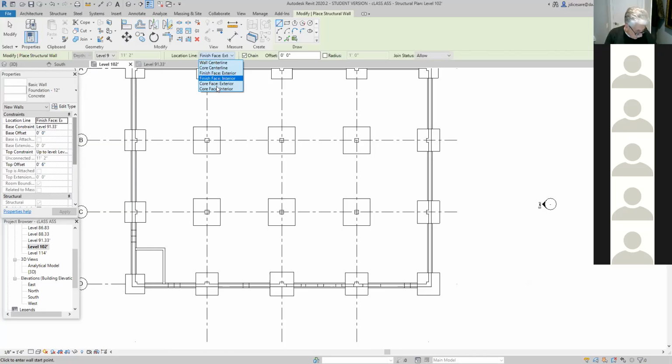If you look at the overall dimensions, they seem to be placing the walls with the finished face outside. So you put finished face outside. But don't worry if you make a mistake, you can flip the walls, but you should take this into consideration: finished face outside. Now, you notice you have it here, you even have it here. So that's one thing about Revit. Too many places that you can do this. Finished face exterior.